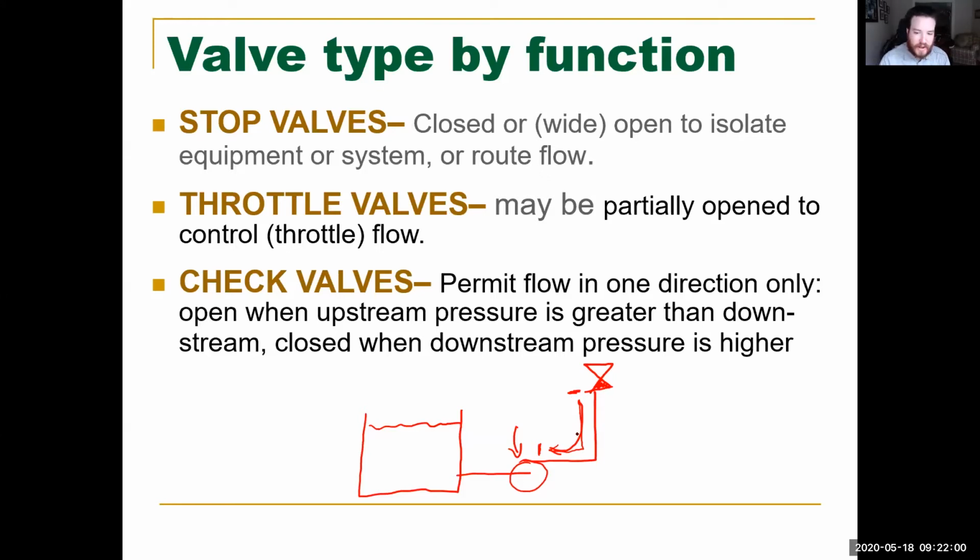That's why you would want to have a check valve in this instance, because the pump turns on, it pumps up, it goes past the check valve. Once the pump turns off, the upward flow going through it stops, so the check valve closes. Now all the fluid that is on top of it is keeping the check valve closed, and that pump won't just continuously cycle. And that's a really good instance of why a check valve is needed.